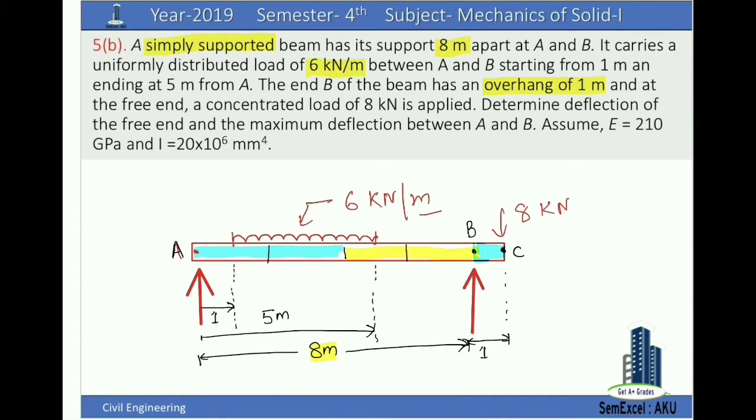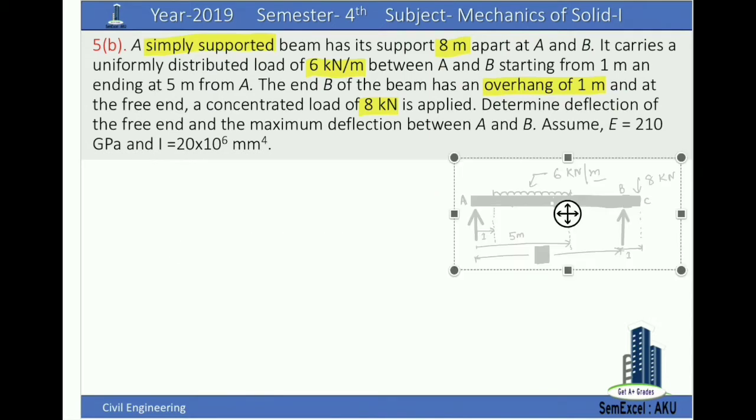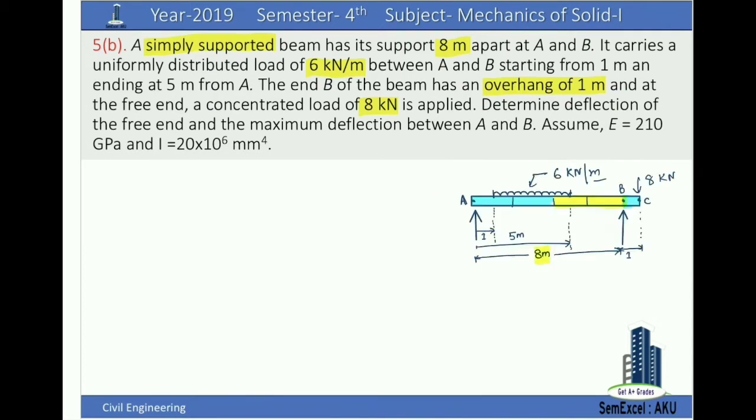And we have a 8 kN load applied at the tip of the overhang, and what we have to determine is deflection at C and maximum deflection in this range. So let's start. The very first step is calculation of reaction force.